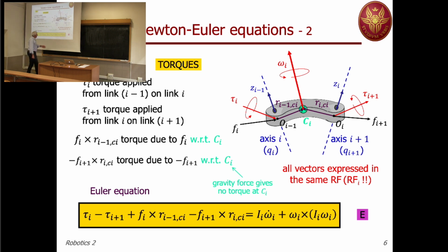We have computed this for a generic body. Now we are writing this for the body I. So it's inertia matrix I times angular acceleration omega dot I, and then this cross product, which involves twice the angular velocity omega. Again, this yellow formula will be labeled by this violet block with a capital letter inside. E stands for Euler. Of course, you have guessed correctly. Okay. And again, we have the angular acceleration of body I.